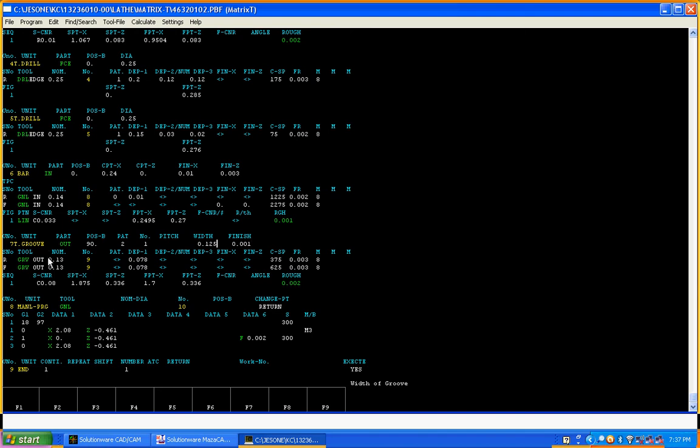It's going to tell you something's wrong. Okay, and then here on the width, my tool is 125 and the width is 125, so we need to make it bigger, like 128. And this grooving tool is just making the chamfer on the back of the part. That's all it's doing.